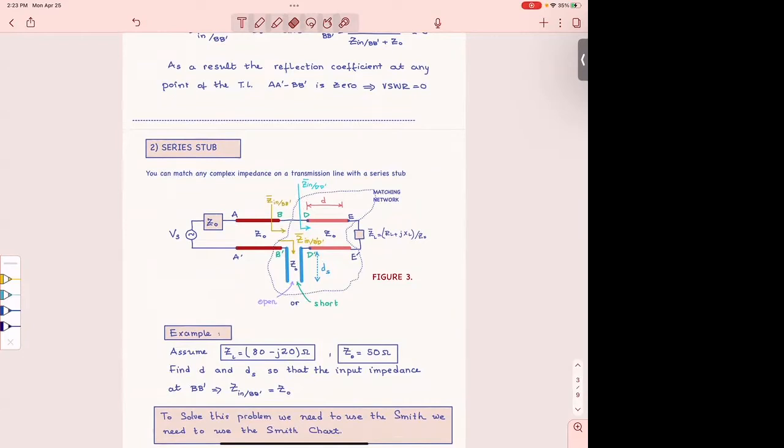And then I'm placing a short-circuited stub. So practically, you decide that this is your solution. No, the other is the solution, short. And in this case, the length of this stub is going to be 0.08 lambda. And then you're done. Then you've made Z input at PP prime to be 50 ohms. And this is 50 ohms everywhere, so it's 50 ohms here, and you're matched to the load.